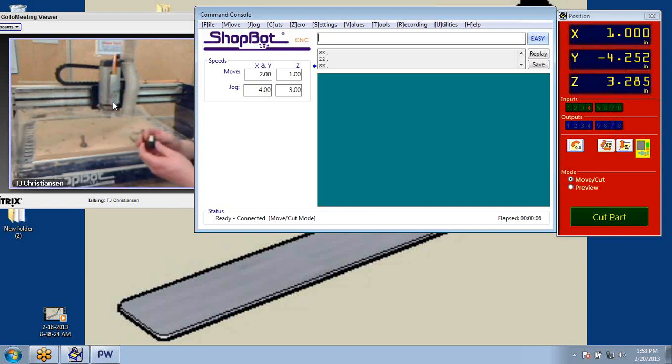Some guys are not doing that, and then they're getting it stuck in here. What will happen is they'll put just this piece in here and then jam this nut up in there, and it'll get stuck. All I know is when people call in and say, I can't get my nut out of there, that's not a good position to be in. So when you pull it off, blow it out, check them, get them back together. Obviously, a Porter-Cable router one isn't going to come apart, but these spindle ones all do.